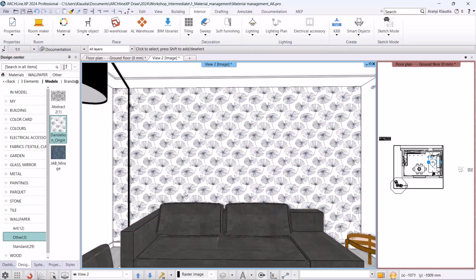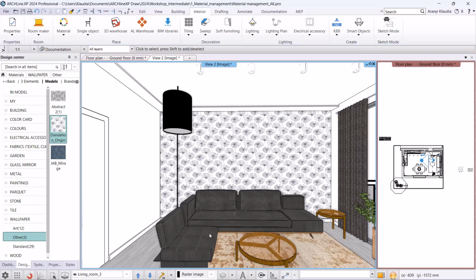In the following, I will show you how to resize and rotate textures in 3D. A texture is globally mapped to a surface in the world coordinate system, independent of the object coordinates. This means that the texture does not stick to any object, but is fixed to the global origin, so that the texture remains untouched by the transformation within the object and does not move relative to the global origin. However, if the object is moved or transformed, the textures move with the geometry of the object.